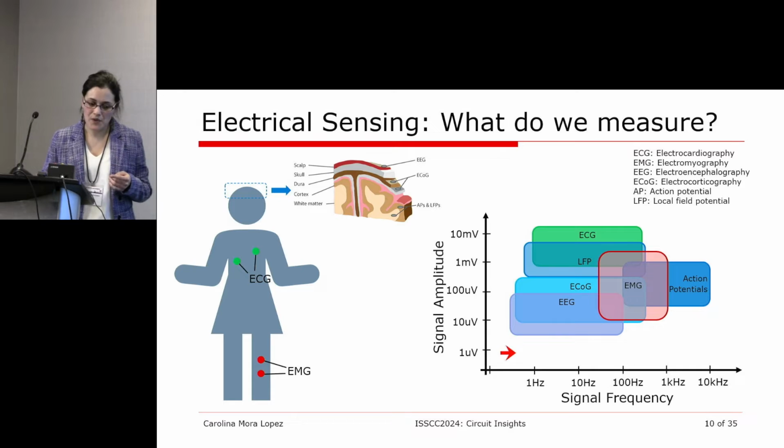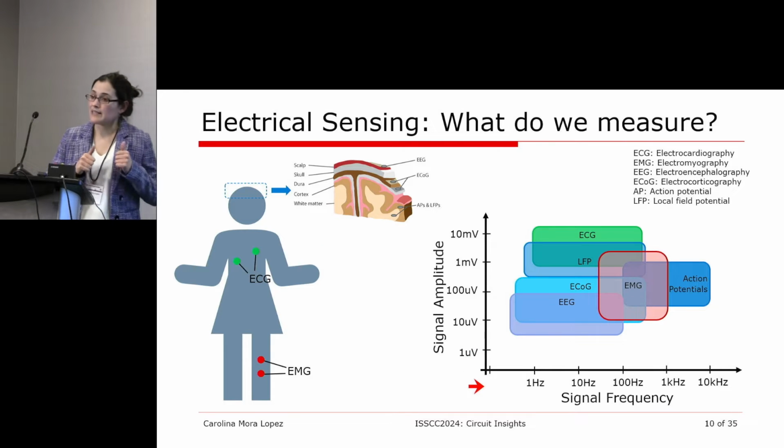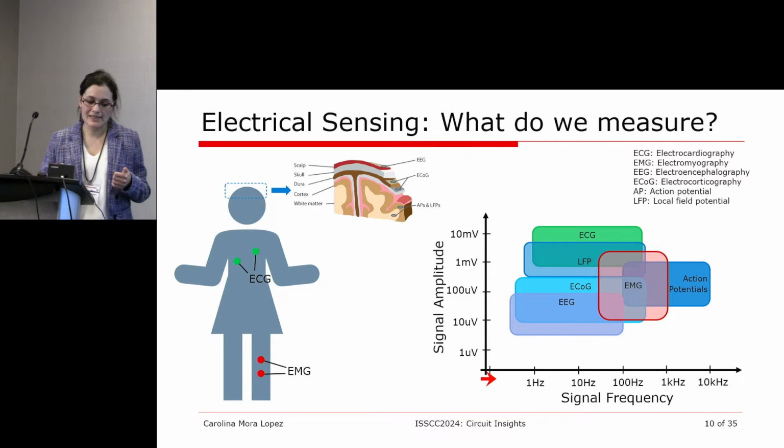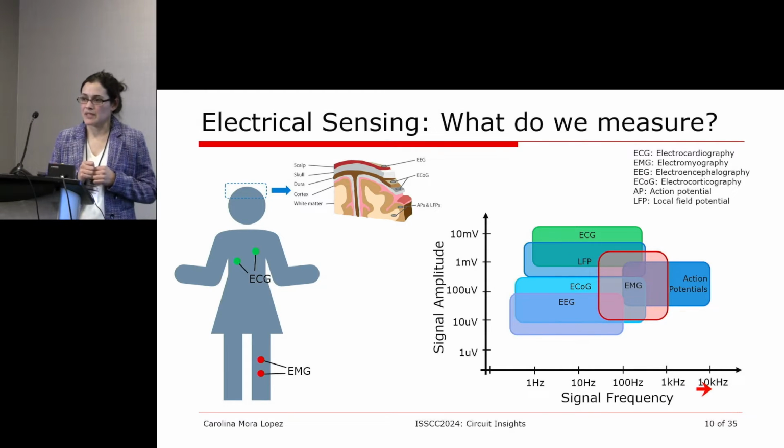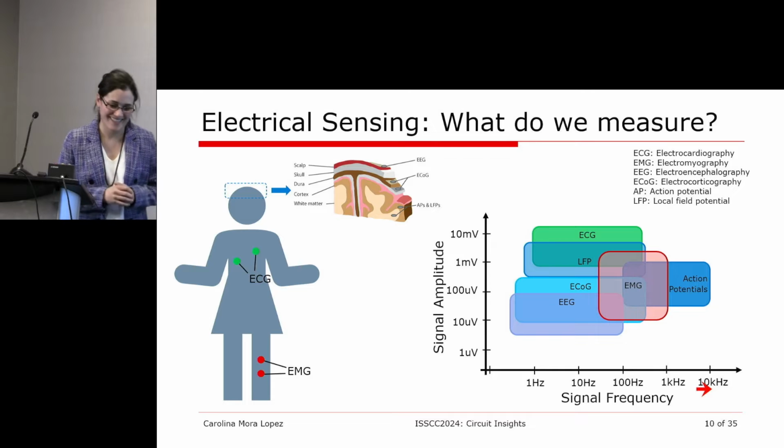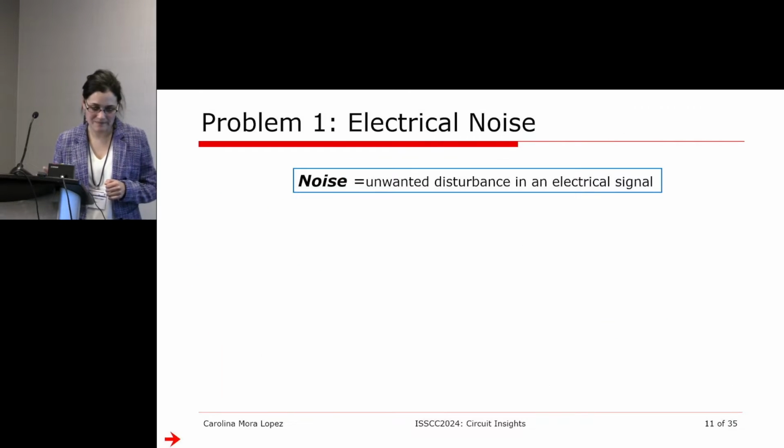They can go from a few microvolts to a few millivolts. And they are also very slow signals. They can start from less than 1 hertz to a maximum of 10 kilohertz. Although for people in this field, they will think 10 kilohertz is your high frequency signals, when we go later to RF, this is actually all considered DC. But what is important is very, very low frequency.